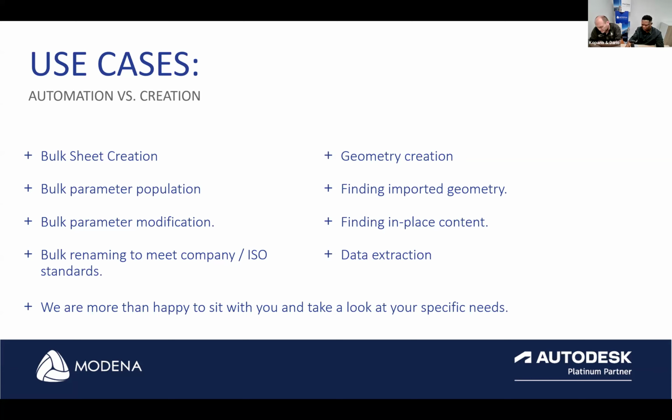Yeah. If I can add to that question, Eric. Another thing that we need to remember is that preloaded families are not system families. So what only sits perfectly within the template is your system families. Your preloaded families sit outside of the template, and you will then link them in as you need for project requirements.